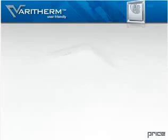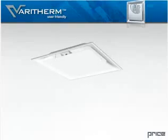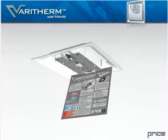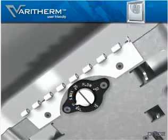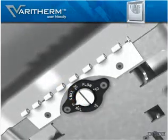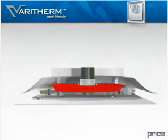User-friendly. The Varitherm is easy to install and use. Simply opening the plaque allows the user to make control adjustments. The plaque pivots securely on a solid hinge and is held closed by a set of powerful magnets. Easy-to-read gauges let you know what your settings are. Temperature is adjusted with the spin of a dial, and the minimum airflow setting is adjusted with the turn of a screw. The unit is also equipped with a forced open mode to assist in system balancing.